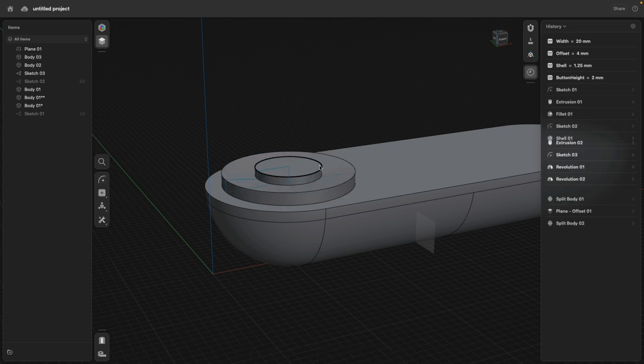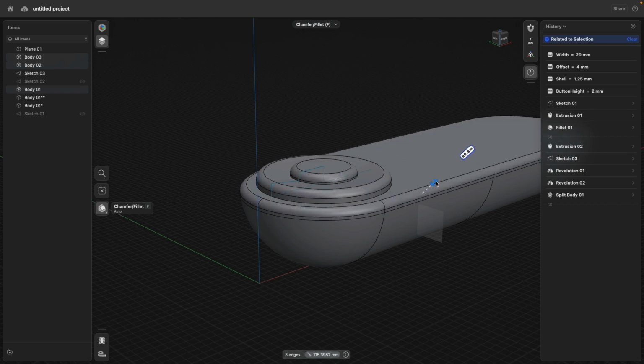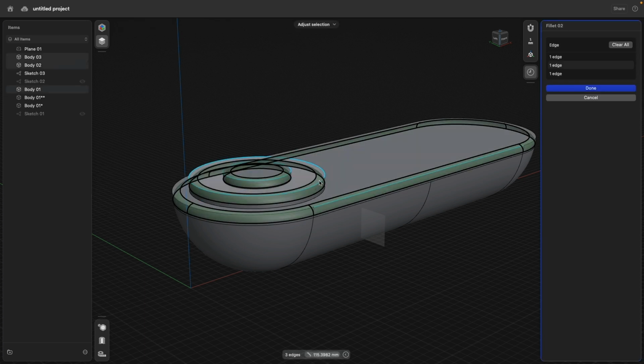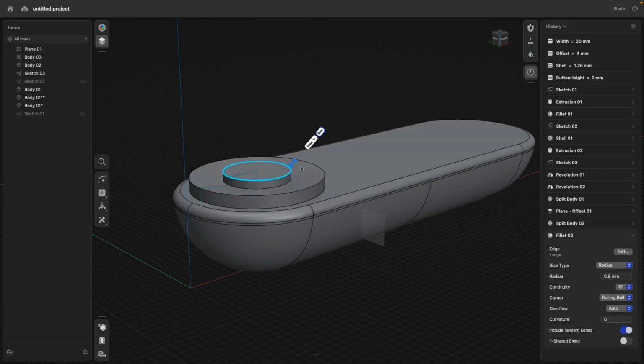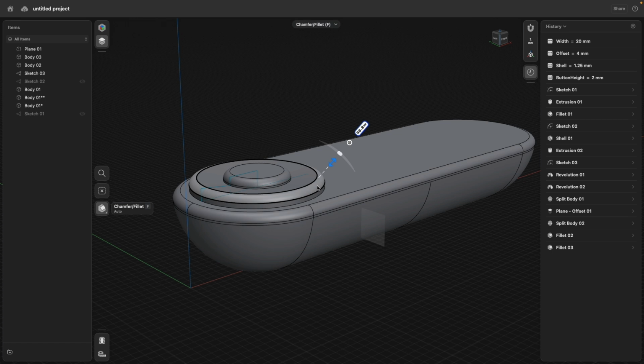Maybe a little bit of tidy up. We can round all these edges there. One thing, that's the main reason why I also did this, is now we have to be careful. If I make these buttons very tiny, then these fillets can actually be more problematic. So in this case, I should actually break this up into two different features. So here's one for the edge and one for the button.